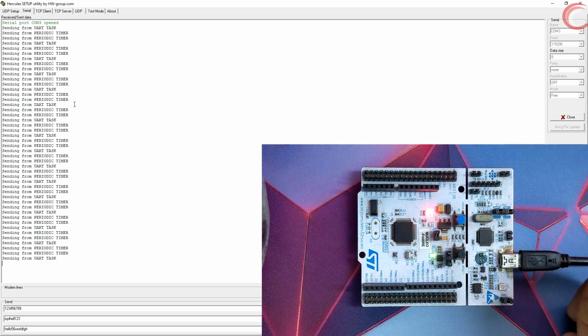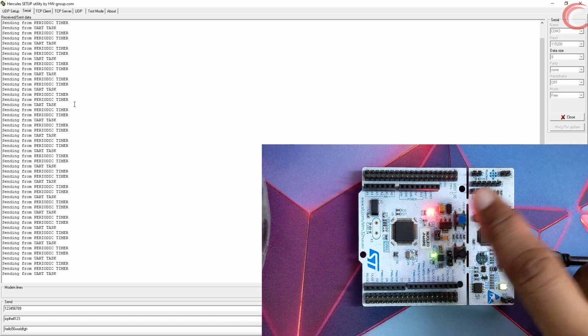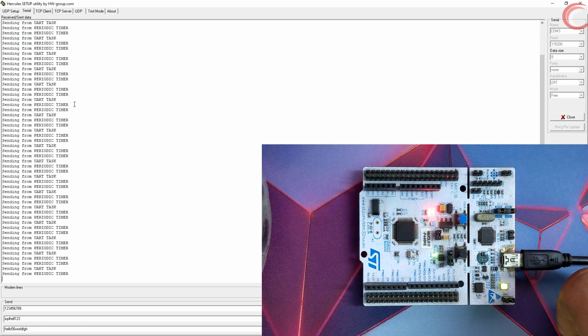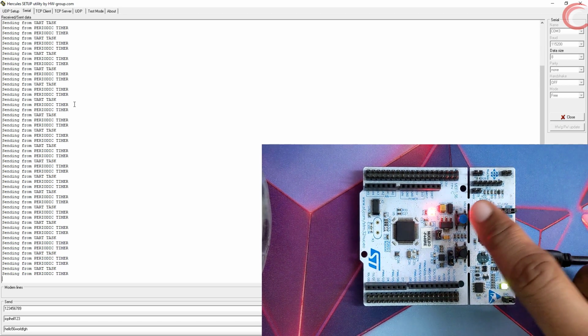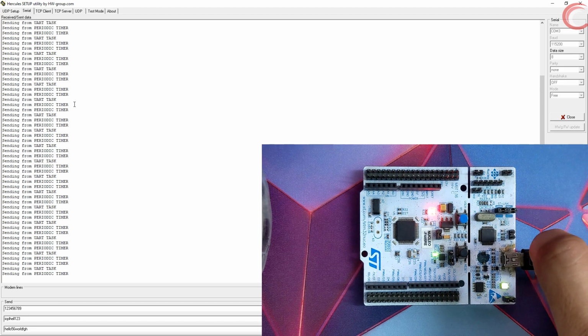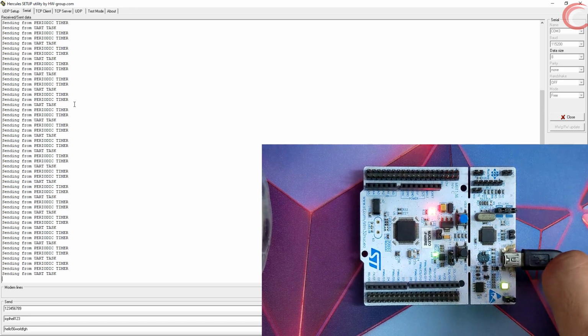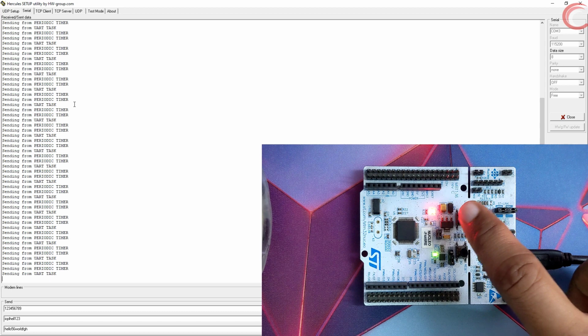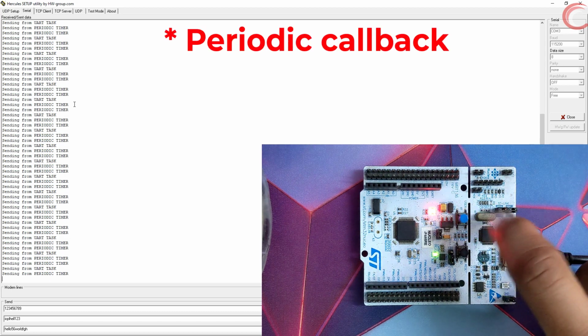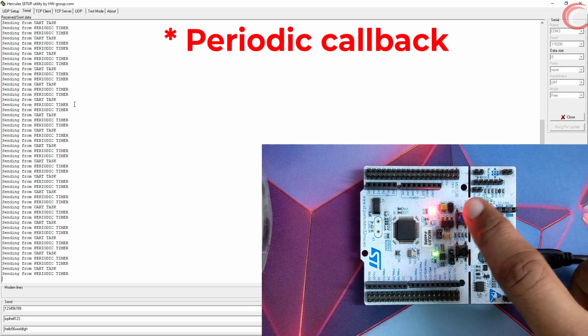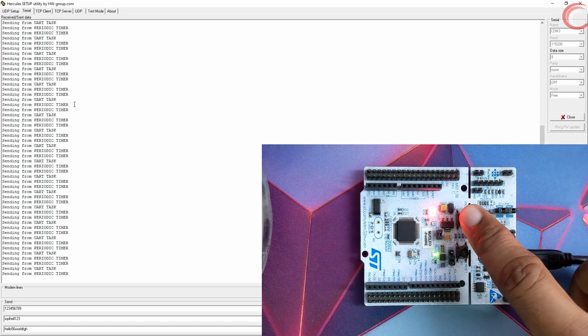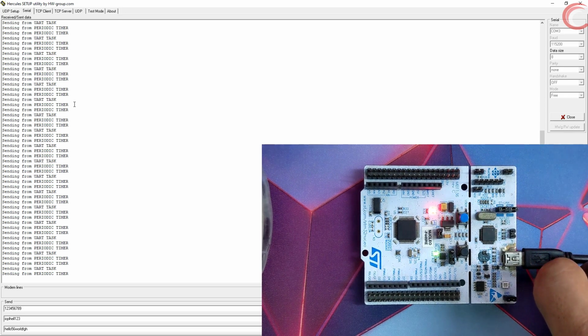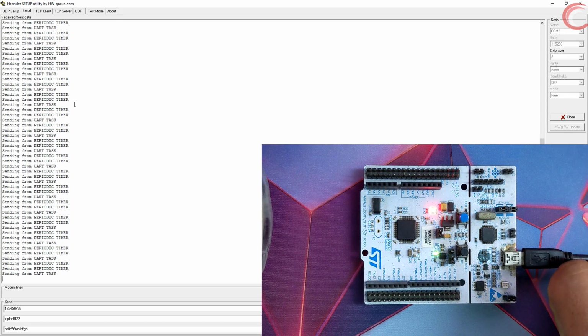The LED turned on. And it turned off after 4 seconds, just as we programmed. But if we press the button before the timeout, the LED will never turn off. You can see the UART task and the periodic tasks are performing just fine, and they are unaffected by other tasks and timers. This LED is similar to the backlit for the display, or any other device, which can be controlled by the timeout feature.